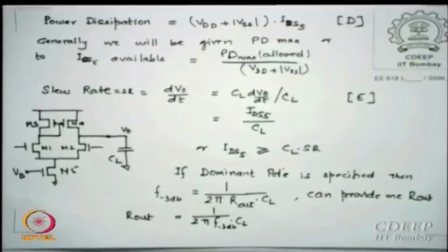So I must know that for a given temperature rise, with the available thermal resistance of the path, I know how much delta P is possible, that is, P possible. So power is limited by the heat sink and not anything else. Is that correct? If you can remove the heat, you can guess from this, your laptops or nowadays iPads or whatever Android based any other handheld system, they have been very low in power for a variety of reasons.